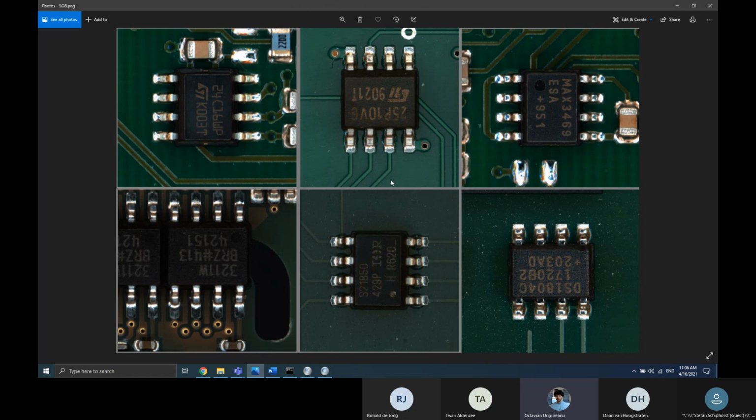And our solution for this problem is being able to record the images from the production. So normally, let's say in a traditional AOI, you will need to have a board with samples from each product, so then you can do optimization. But it's not very easy to keep a sample from each product that you have in your production, and then of course you have to stop the production, load the board, so it's a bit inconvenient working with physical boards.